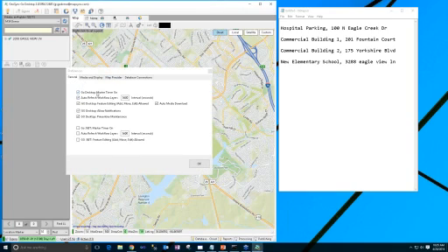Here's our preference dialog. So from the very front screen on here, we would need to see the options that we need to make sure are turned on if we want to do editing. Our GeoSync GO Desktop Master Timer on, Auto Refresh Workflow Layers, and then the Go Desktop Feature Editing and Move and Edit needs to be checked. So default when software is installed is these two items are checked, but the feature editing is unchecked. So you've got to make sure that that option is checked, and we're good to go.